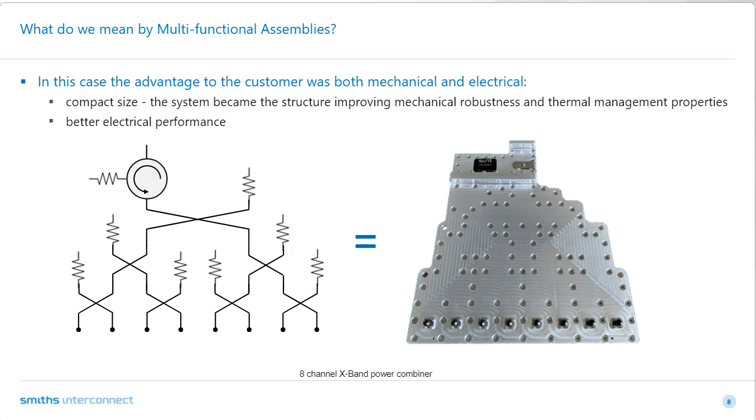Understood. And to summarize that, besides the footprint and obviously the less insertion loss, the thermal characteristics of this package as it related to the amplifiers was critical. Would you agree? I think looking back, it wasn't immediately clear at the outset that the thermal problem was the problem to solve. But at the end of the program, looking back, certainly the number one advantage of this was the thermal management properties of this device.